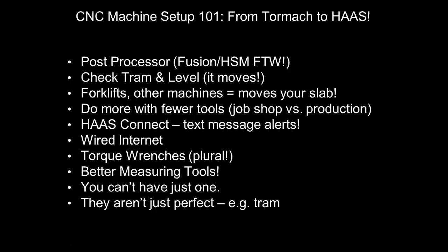Post processor, make sure you've got a post ready for what you're trying to do. A big shout out, I think it's been a bit of a game changer that when you download Fusion 360, you get 50 or more default post processors for everything from Tormach to Fanuc to Haas. And we're using the default Haas.